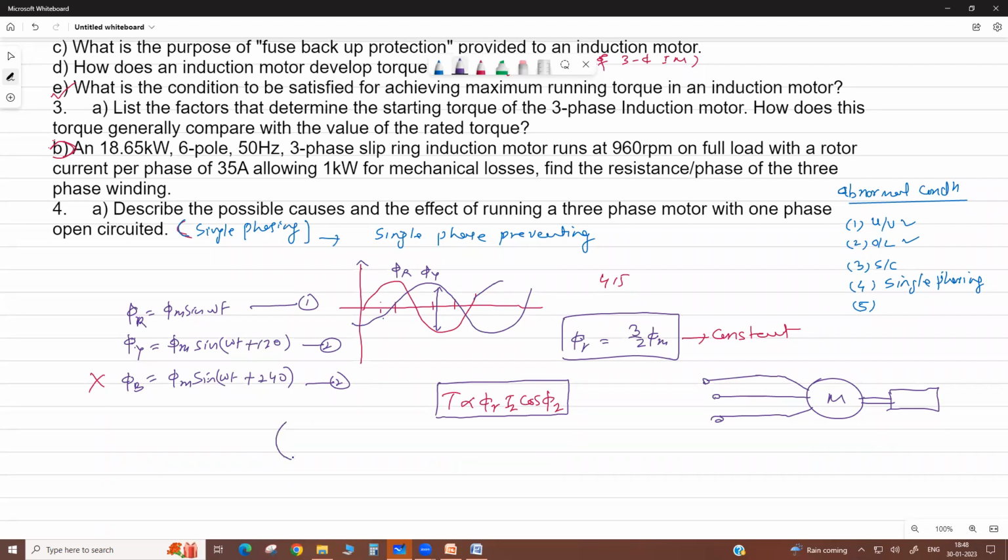Negative sequence harmonic is increased, so there is a negative flux in the air gap, the negative sequence harmonic flux. Due to this negative sequence, the slip is double, 2s. The rotor copper loss is slip times the rotor input, so the rotor copper loss will be double in that case.